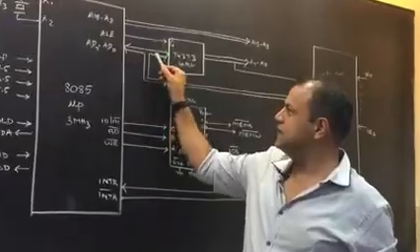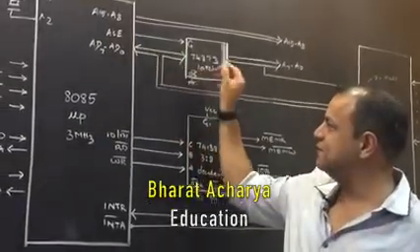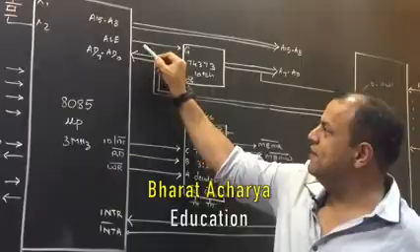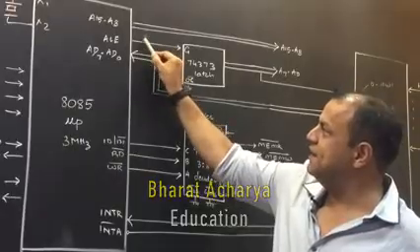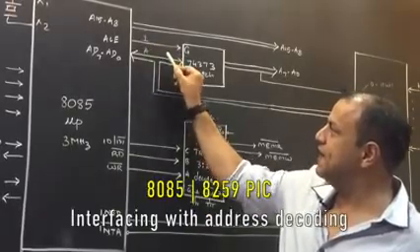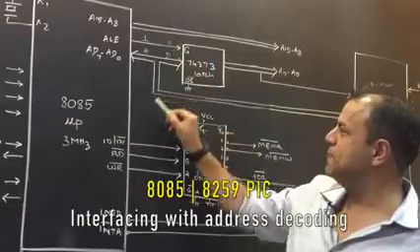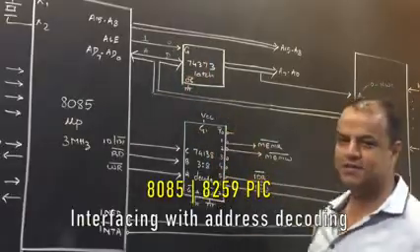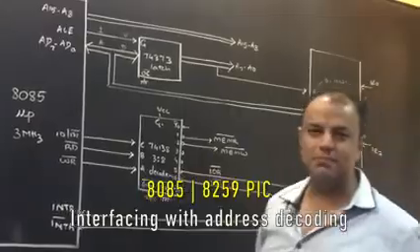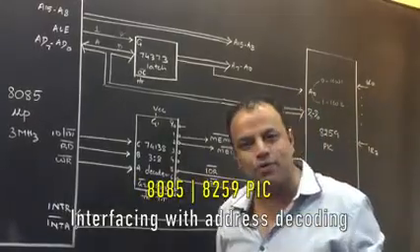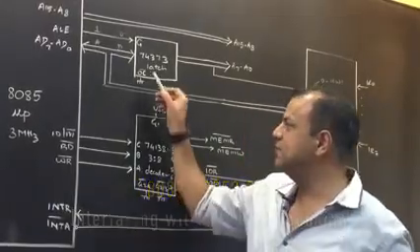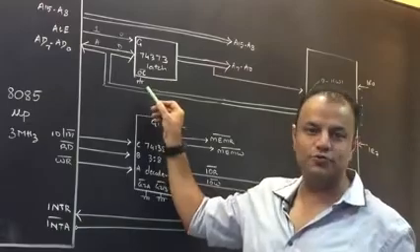This bus initially carries address, then carries data. When this bus carries address, ALE is 1. When this bus carries data, ALE is 0. Now, we give this bus to the latch. There are two signals on the latch. OC bar, output control, is an active low enable signal. It has to be always enabled. Active low means it needs a 0, so you connect it to ground.